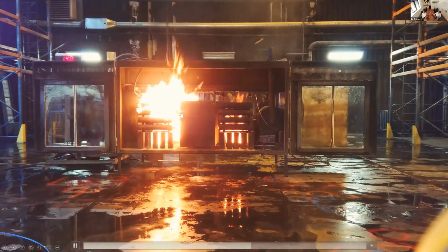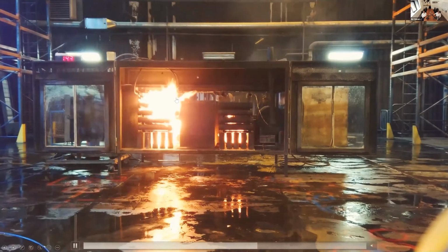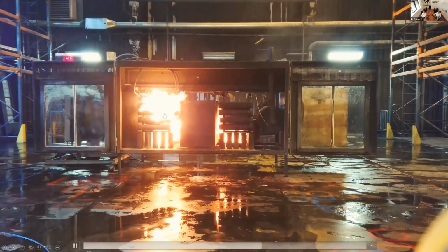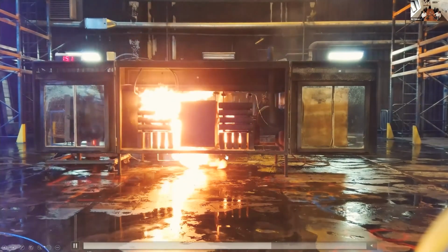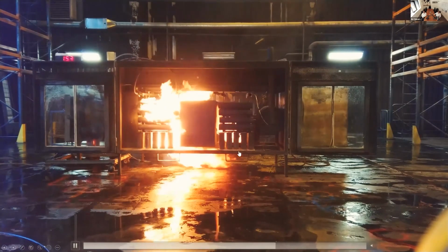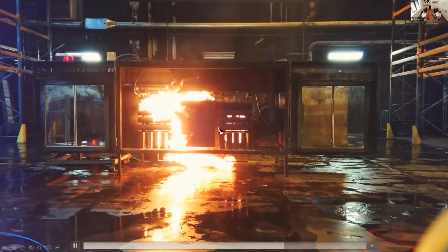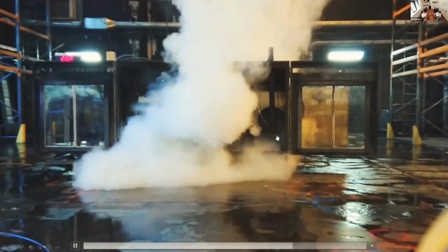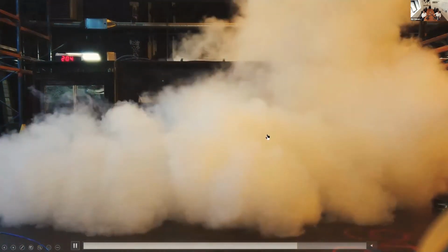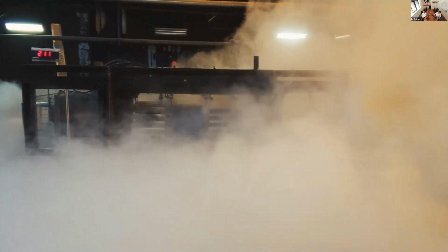So you can see very quickly that as the airflow increases, it changes the dynamics of the fire. It also increases the white heat that you see in this area. And then we add a liquid spray that you can now see has fueled the fire even further. And then at 2 minutes, we manually activate the system while the diesel spray and fan continue. So what we're testing for here is that we see no reignition. We continue the discharge of the dry chemical for around 10 seconds.